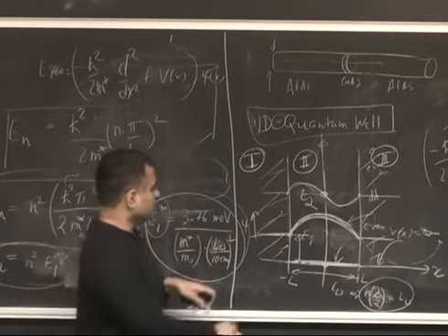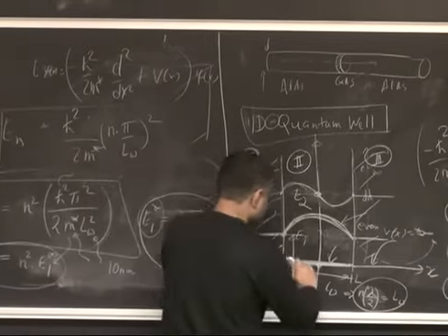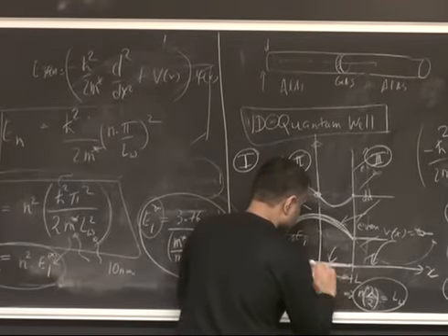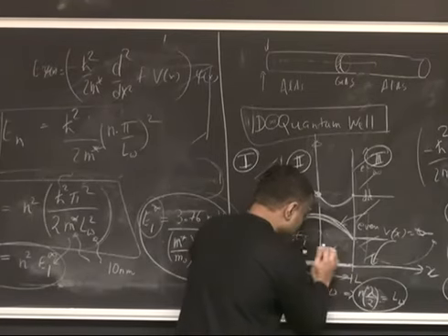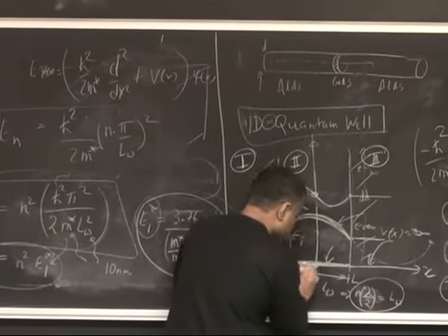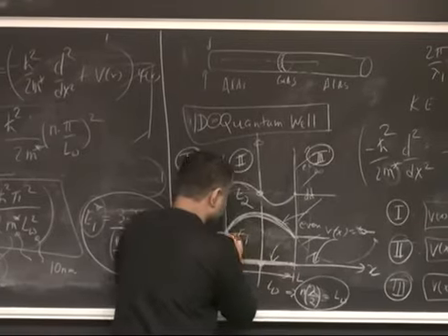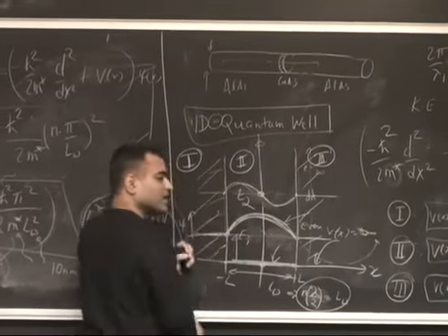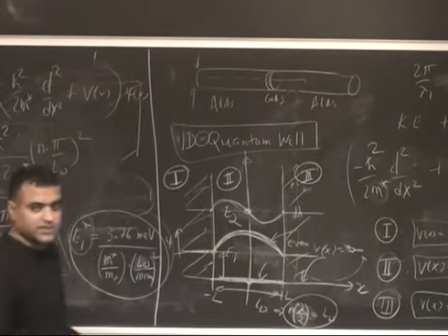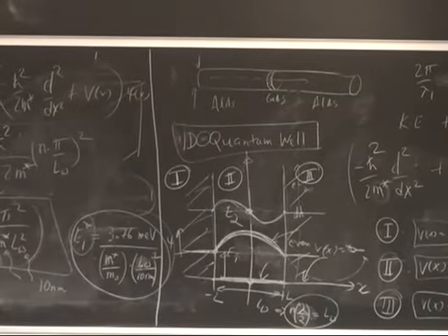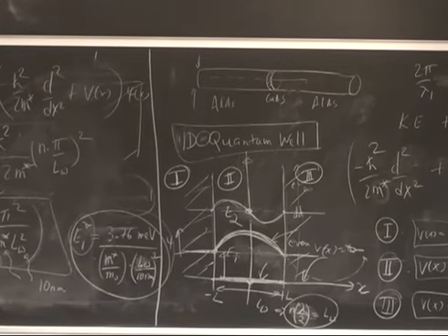So in that limit, if I had gallium nitride or gallium arsenide, this will become the band edge of that material. But if you have a quantum well, the band edge of the bulk semiconductor is still here, but because of quantum confinement, the lowest allowed energy for an electron in that layer is not there anymore, it's up here. So that's the meaning. And then you have a gap in between the two. Okay, more questions? Is that clear?